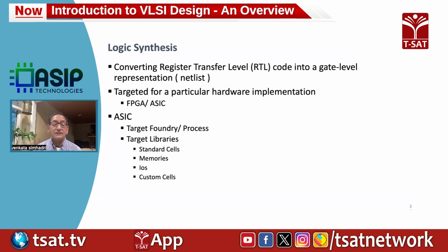Similarly, memories. Most EDA companies and IP companies also supply memory compilers. TSMC has its own memory compiler, for example, and these compilers you can use to create the memory blocks you need. If you need a single port, 1 megabit SRAM, you can use the memory compiler to create one.